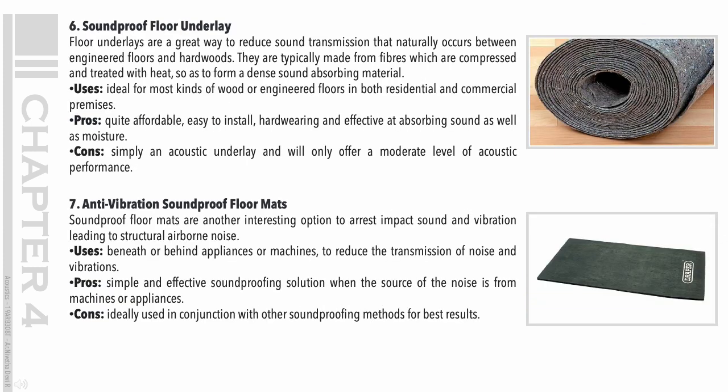6. Soundproof floor underlay. Floor underlays are a great way to reduce sound transmission that naturally occurs between engineered floors and hardwoods. They are typically made from fibers which are compressed and treated with heat, so as to form a dense sound-absorbing material. Uses: ideal for most kinds of wood or engineered floors in both residential and commercial premises. Pros: quite affordable, easy to install, hard-wearing and effective at absorbing sound as well as moisture. Cons: simply an acoustic underlay and will only offer a moderate level of acoustic performance.